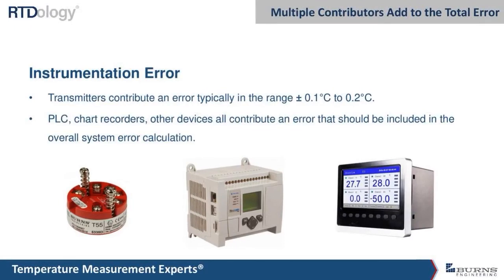I think finally here today, the instrumentation, anything you connect up to this temperature probe, whether it's a PLC or a chart recorder, data logger, or transmitter, they all have error sources with them. And it's another one that needs to be accounted for in any kind of total measurement calculation.